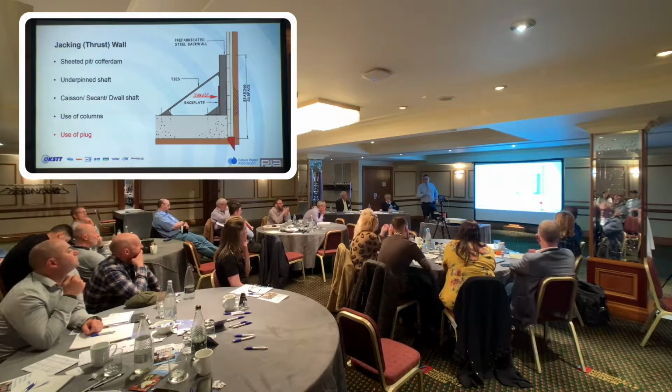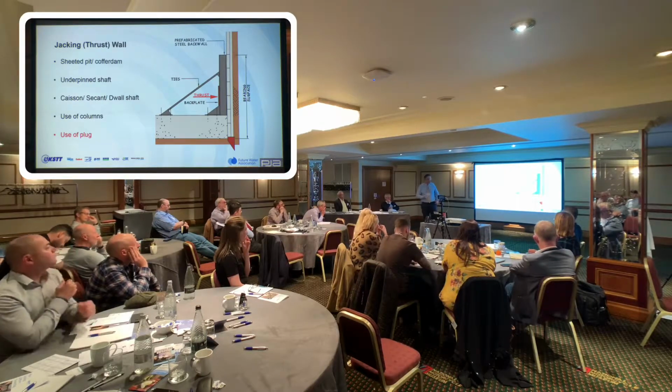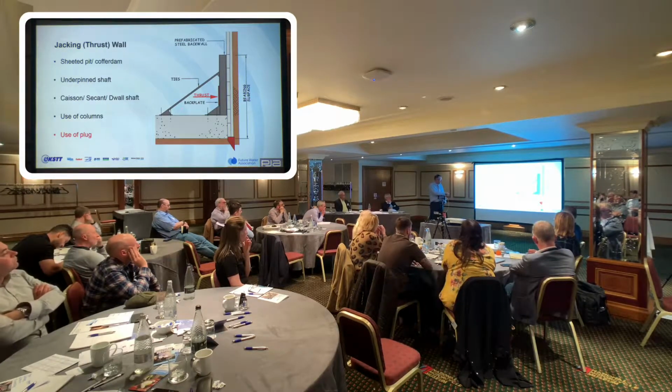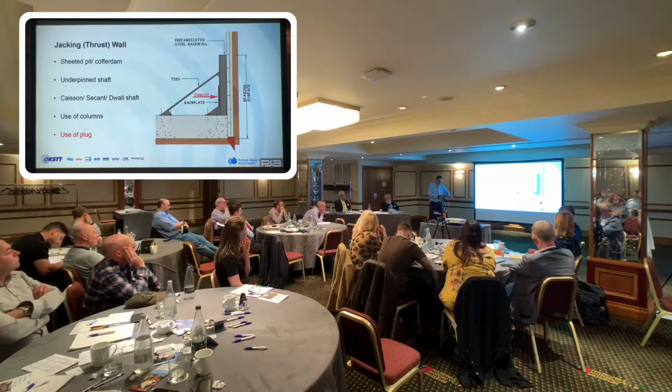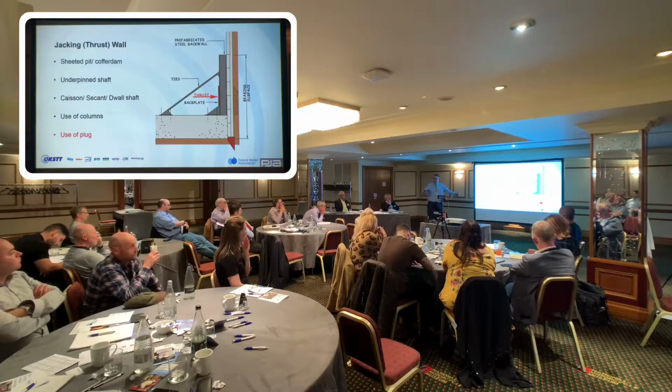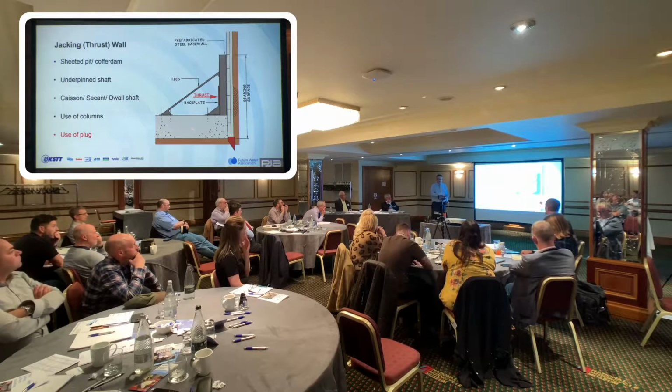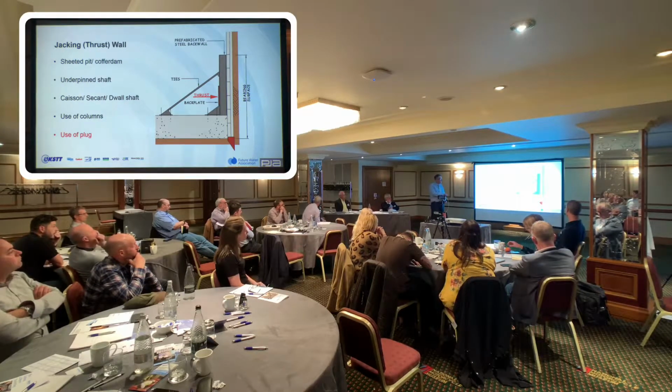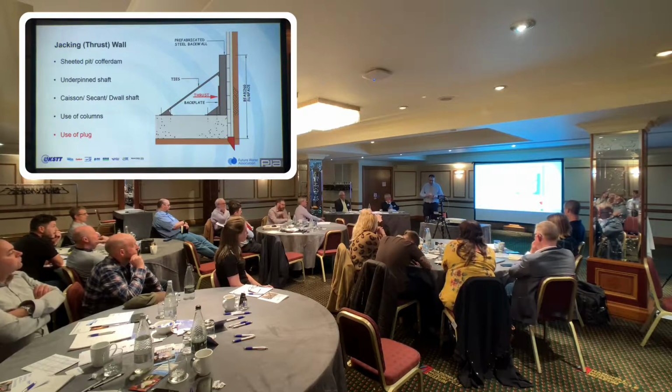But I have seen where you may not want to load that back wall at all. I have been involved in the past where this structure, if you like, has been in a bigger shaft, and the actual frame has been bolted, if you like, in the middle of the base with no connection to that back wall. Again, I'm not that keen on them personally, because you're relying on these connections doing an awful lot of work. I'd be more inclined to cast stuff in, to take some big members, big sections, and cast those into the base.